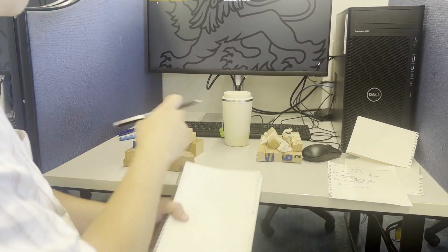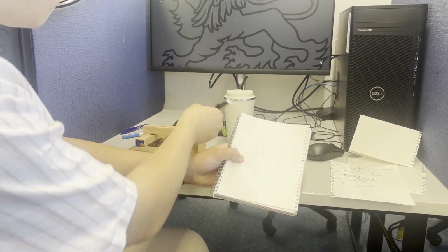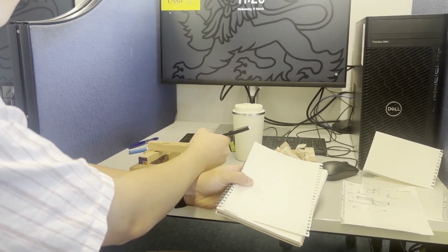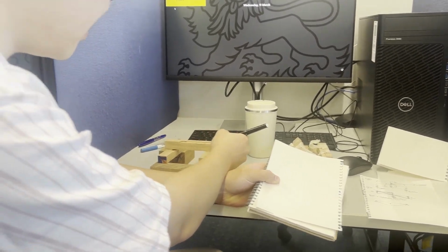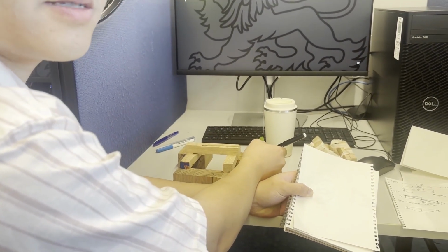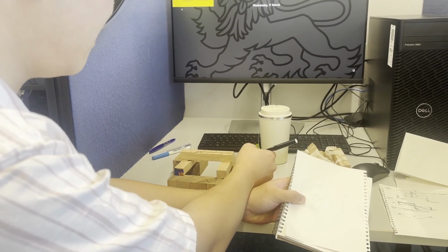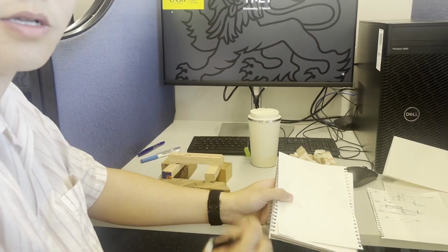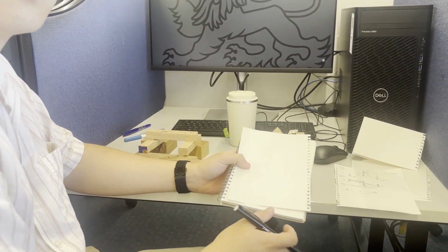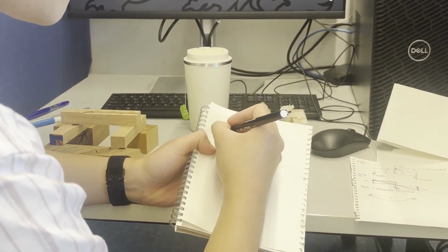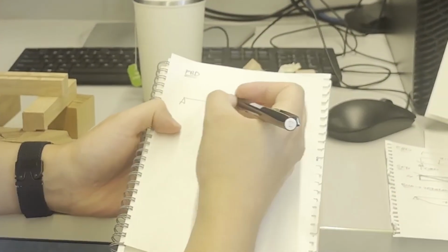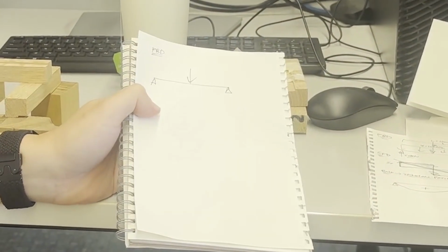is that when it loads the primary beam, what happens from here to here? This support is a reaction, okay? But that reaction now becomes a new point load for what it's supporting. So the thing that's supporting it, which is the primary beam, that reaction now becomes the point load. Right? So someone said before, is the free body diagram of the primary beam a point load? And you're right, it is a point load.